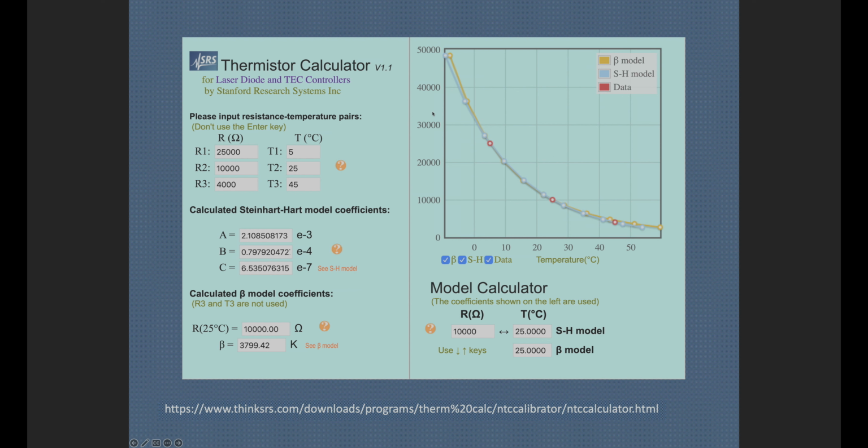And this is going to be our setup for our test, to get our baseline readings for both of these thermistors. You can see we have our reference closest to the thermistors that we're going to be measuring. We have our reference temperature, and we're looking at the resistance value that we're going to obtain. And we're going to do it like the manufacturers. Most manufacturers recommend you do it in a silicone bath, not water or air, to give you more accurate and more stabilized readings. It's not hard to calibrate your own response curve.